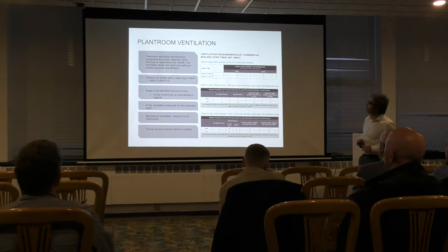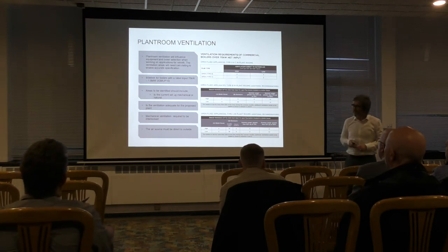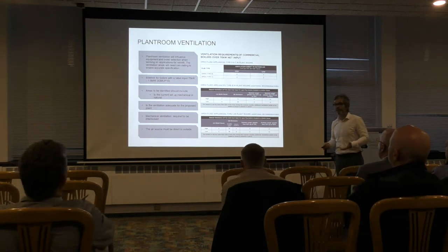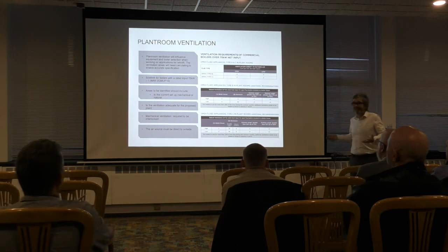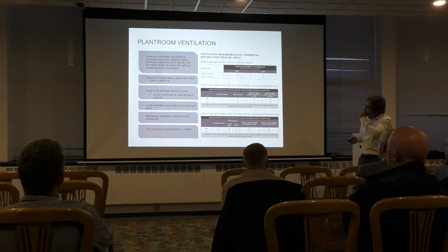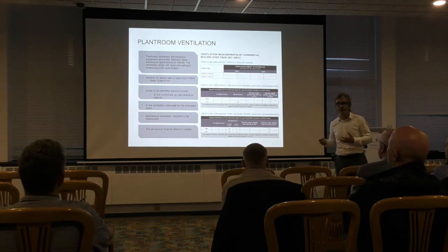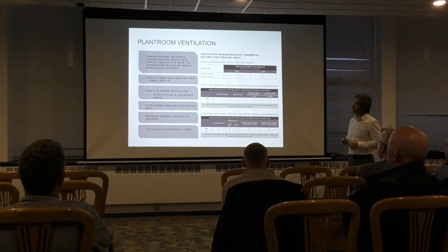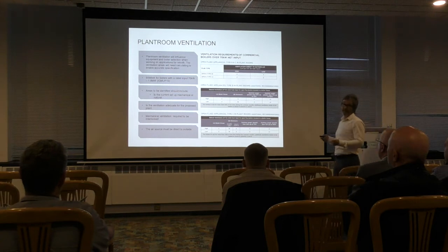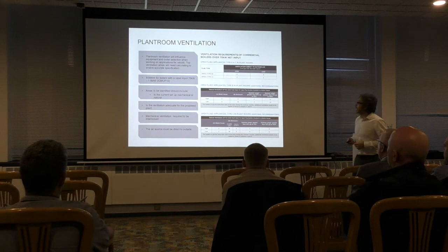Now, moving on from there, going on to ventilation. Ventilation, as you know, is really, really important. Anything that burns anything needs oxygen to do so. Obviously, with boilers, we're burning gas, so we need adequate ventilation. Two pieces of guidance and legislation that we would always guide you to are BS 6644 and IGEM UP10. They're really your go-to guides for ventilation and flues.